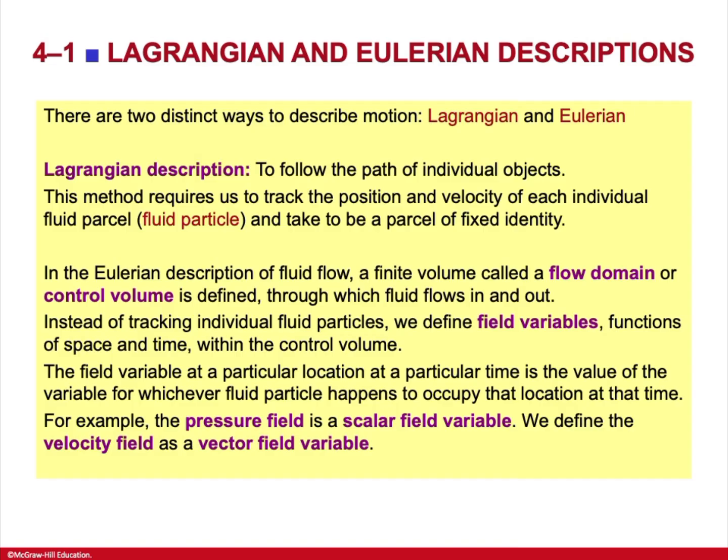You are technically following every particle as it deforms, because the atoms are bound to their lattice sites and vibrate about them. So in solid mechanics, you're often observing each particle as it deforms. It's convenient to do that for solid mechanics because of how the lattice structures are confined to their lattice sites.